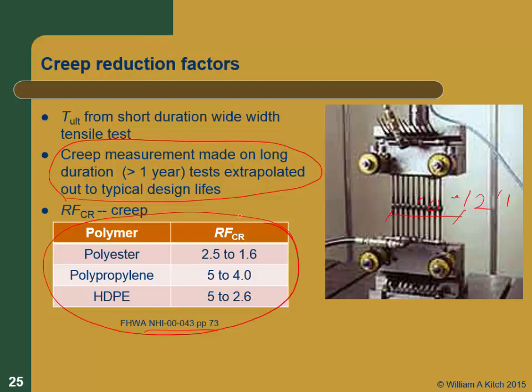So some of these are a combination of HDPE and polyesters that they try to optimize for both characteristics. It is kind of black magic about what actually goes into these things. You know the basic constituents of them, but you don't know exactly how they manufacture their plastics. So it's really important that you get the performance data from the manufacturer. You need to make sure you're using the performance data from the manufacturer for the material that you're using.